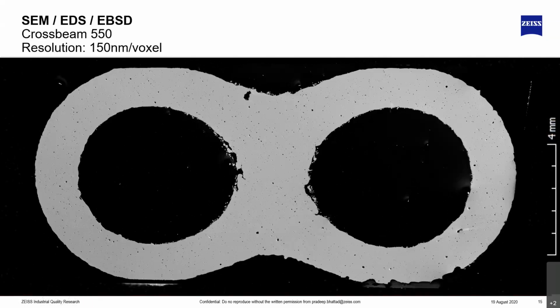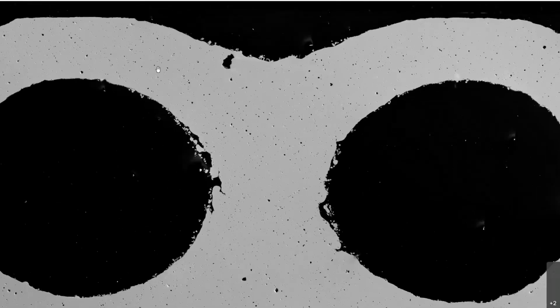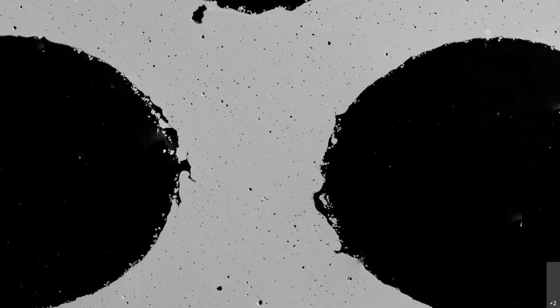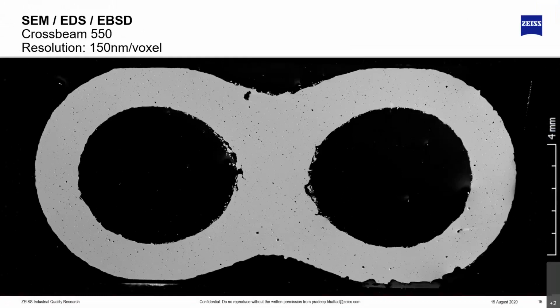Then we can add SEM, and one of the advantages with SEM is that you're not limited by resolution anymore. You can zoom in anywhere you like on the part, walk around, and look at the same part at much higher resolution. You can start looking at the powder particles which are sintered to the surface. And it allows you to add an even higher level of detail to the imaging. At the same time, try to understand: if you are looking at the fuel flowing through this part and some of these sintered powders become loose during operation of the aircraft, that can cause a lot of problems.